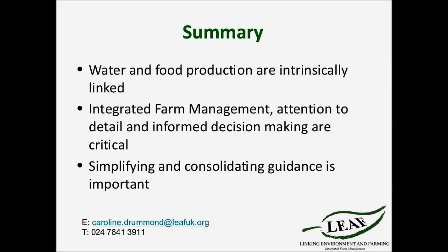And as there become more issues, or you think that there might be a problem, it's working out where the priorities are. At the end of the day, an inline meter is not very much money. It helps identify where the water is being used. It helps very quickly identify where there are leaks, if there is a problem, before it's too late, really. Because it can cost a lot of money, particularly if you're using mains.